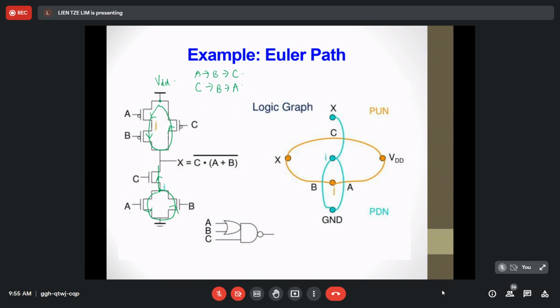In this pull up network, CBA is valid. In pull down network, CBA is also valid. What I mean by valid here is the path must pass through each of the transistors in only one direction, cannot reverse, cannot overlap.